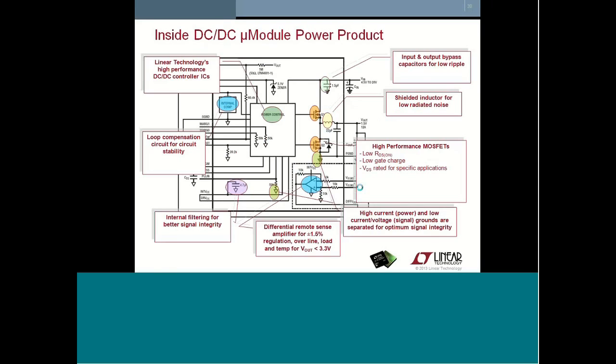Micromodules are DC-DC systems in a package, protected by a plastic mold against outside influences such as touch, scratch, chemicals, etc. Micromodule regulators are built using newer technology silicon, the DC-DC regulator, and MOSFETs. As a result, we have full control of production, testing of the regulator IC and the MOSFETs, so that we can offer the best performance for a particular micromodule.